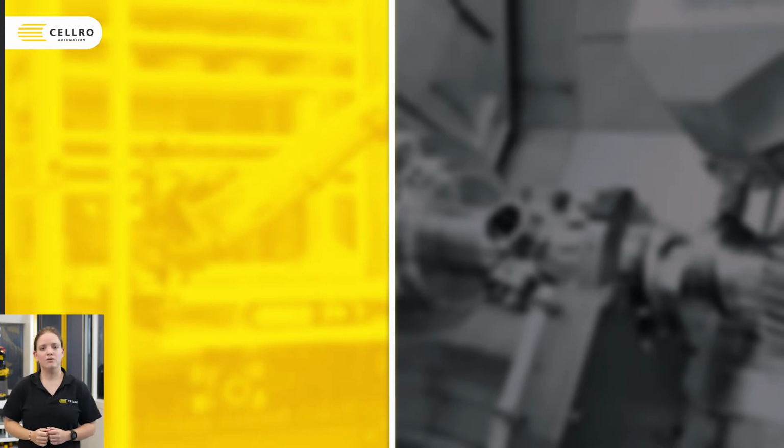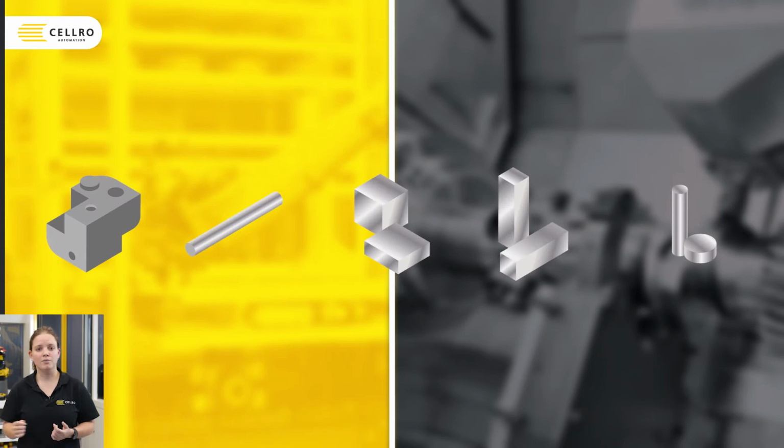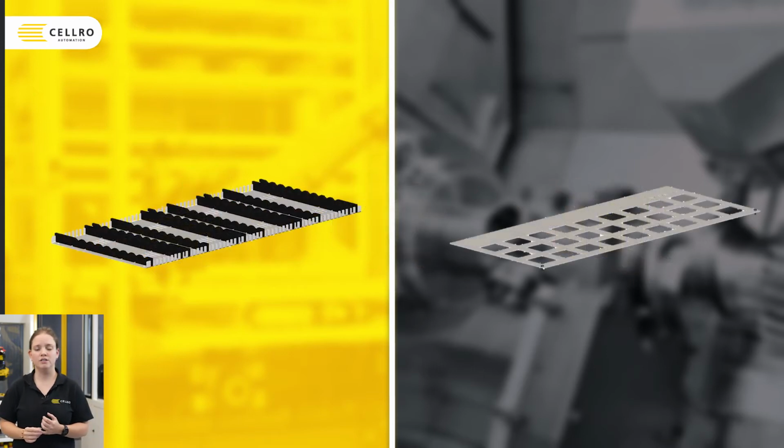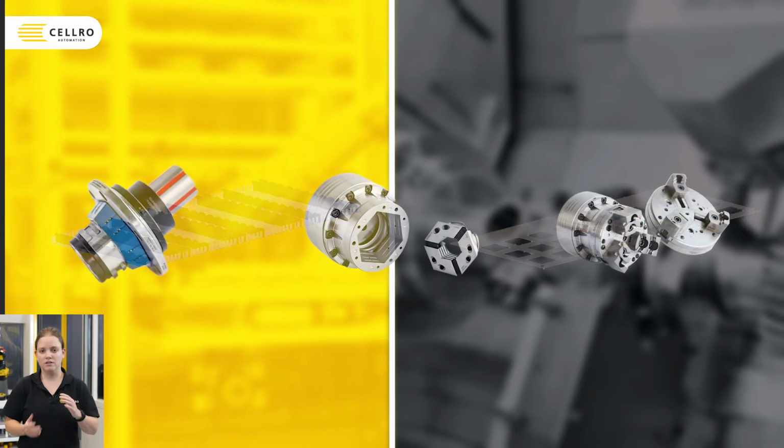First, we start with the robot configuration, and this is the product shape and size, the gripper type, and storage options. And on the machine side, the machine configuration, you may have a 3-point clamp, which opens either inward or outward, or a collet clamp, or maybe a mandrel. Now, on this collet clamp, we'll discuss more later.